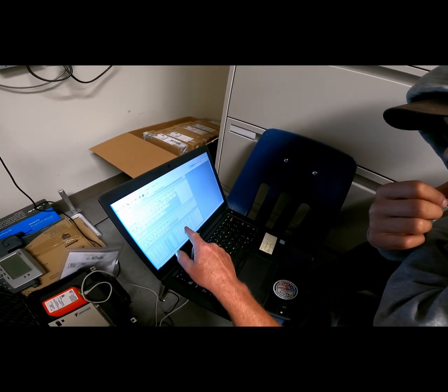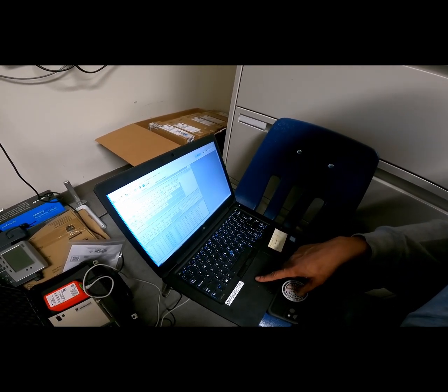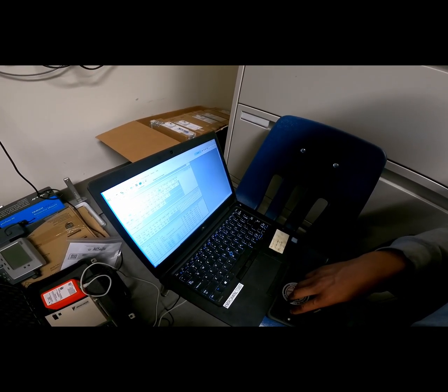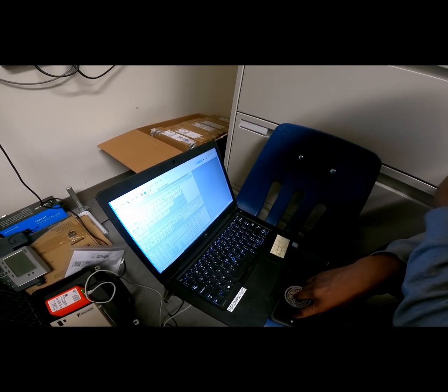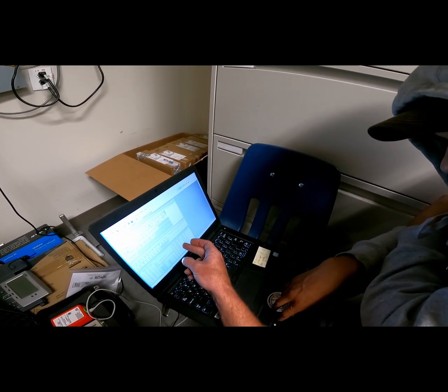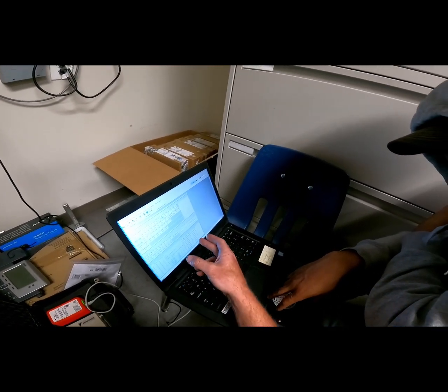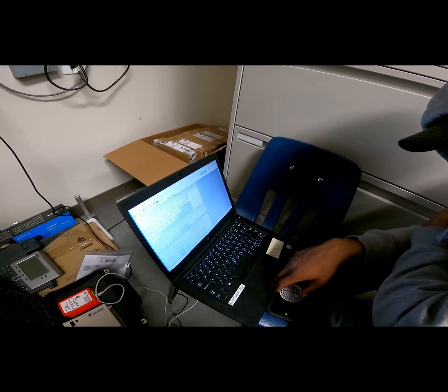But right now it shows us every one of these. Click on OF real quick and see what it says that means. That means operation on/off. Now you see how they're all reading test right now? Yep, they're all reading cooling. And did you see how those went from standby to on? And this one's still in standby? They are now all in cool mode except for that one, and they're all with a high fan speed.